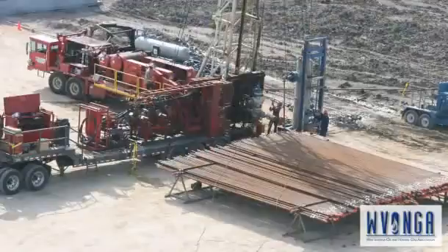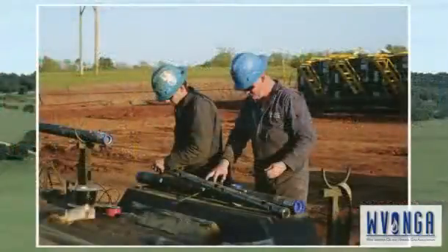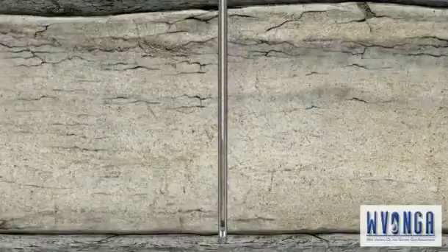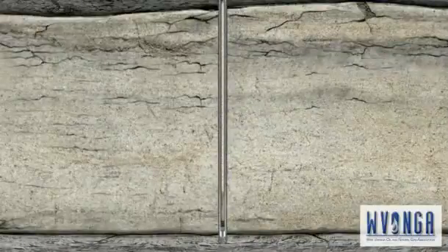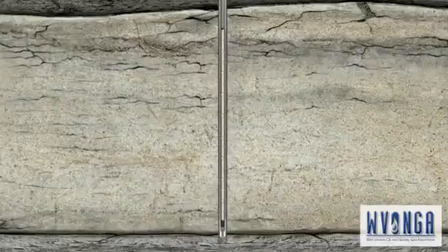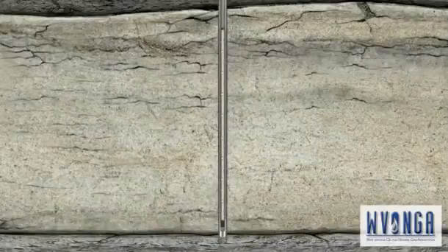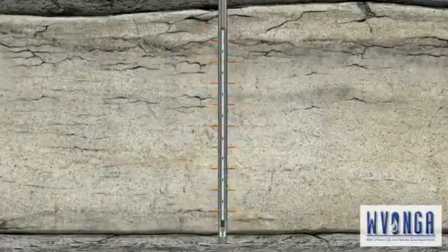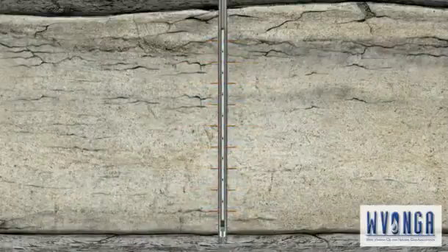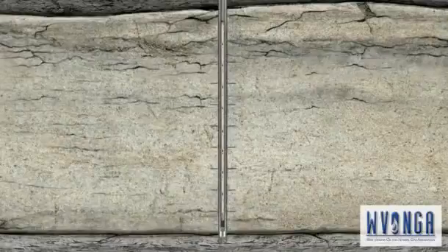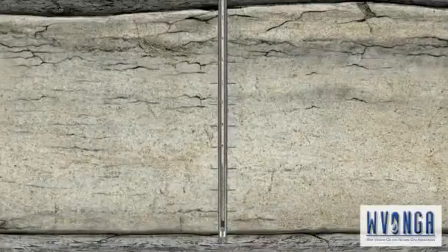The first of these steps is to perforate, or perf, the casing. A perforating gun is lowered by wire line to the lowest of the 3 target zones. An electrical current is sent down the wire line to the perf gun, setting off a charge which shoots holes through the steel casing, cement, and out a short distance into the target formation. The perf gun is then pulled out of the hole.